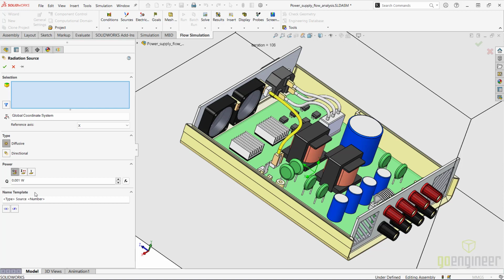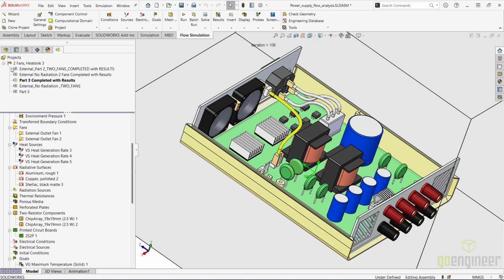An example of this could be, again, a strong light source or furnace operating next to your electronics enclosure that can be specified as maybe a box or a cube that you model in SOLIDWORKS and incorporate into the flow project. For us, since we don't have anything like this right now, we'll go ahead and close this and just continue on without this feature.